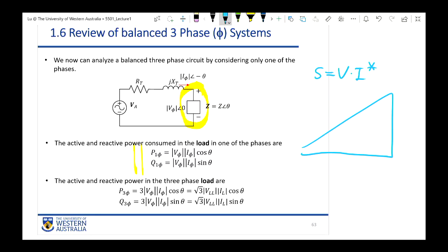In this power triangle, we have all the key factors included. This S is given here. S is a vector having the magnitude and the angle. Okay, this is S. The horizontal edge of the triangle is actually the projection of this complete power on the real power, on the real axis. This is actually the real axis. This segment is actually our real power in the unit of watts.